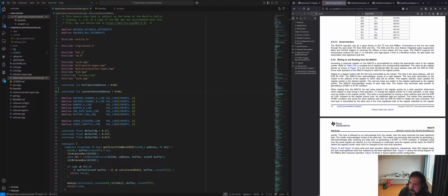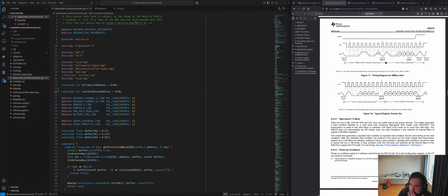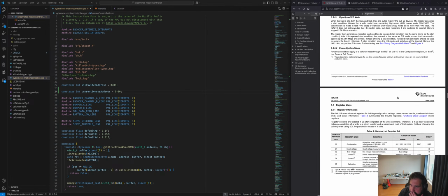Okay, so the question is, if I want to sample all three registers and just cycle through them, do I have to keep changing the address, or will it do what I2C EEPROMs typically do in auto increment? This makes it seem like it probably doesn't. So I will try both. Nothing will hurt it. Okay. So read that. It's just standard I2C stuff.